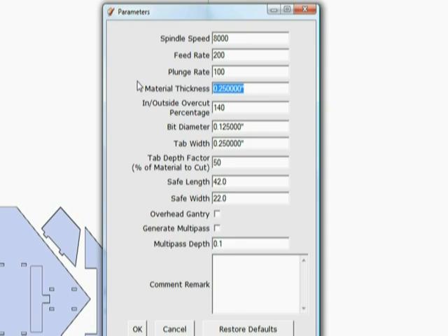Go to the preferences and go down to the units, and I could change it to millimeters if I wanted to, and it would change the document wholesale to millimeters, and I wouldn't see 0.25 here, and you could put in whatever thickness of material that you have. I'm just going to leave mine at 1/4 inch. I know that that works really well with fan fold foam.